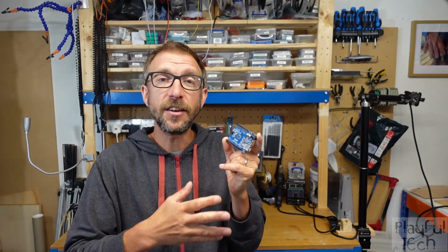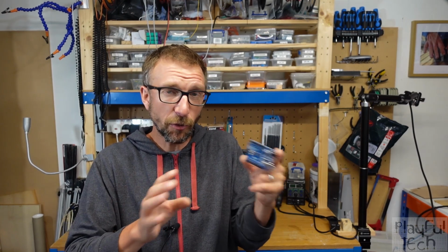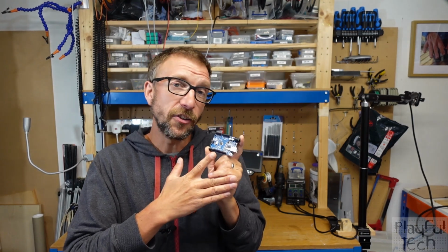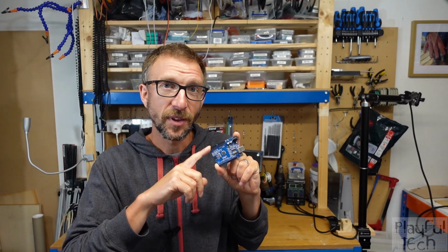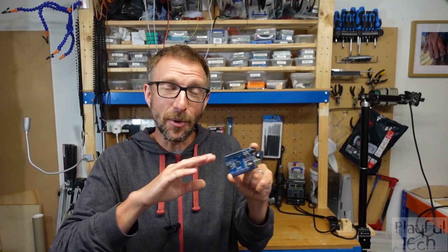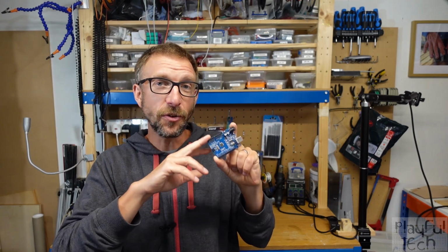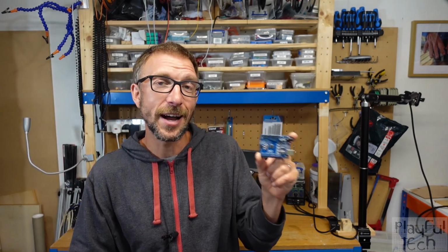Now, there are specific driver chips for things like LEDs and stepper motors, and there's also general purpose transistor arrays. You'll see a lot of projects use chips like UDN2981 or ULN2803, which allow you to switch 8 channels of high current from 8 GPIO pins. But remember, generally speaking, you don't want to directly source power for anything from a GPIO pin beyond maybe a simple LED. You just use that for transmitting data at a logical high or low value.